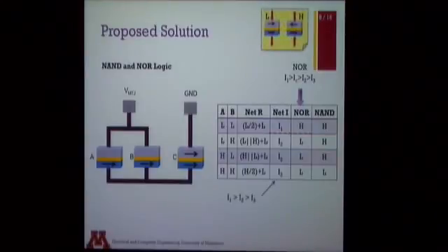So here's your cheat sheet back. When current flows from bottom to top, you get a logic high over here. For the NAND operation, you perform the cutoff at this stage, and so you establish the relationship I2 greater than IC greater than I3, and so for all but the last case, the current flowing through the circuit is greater than the threshold current that writes to this MTJ. So you get a logic 1 here, and the MTJ retains its logic 0 state for the last case. So that becomes the NOR and the NAND operation.